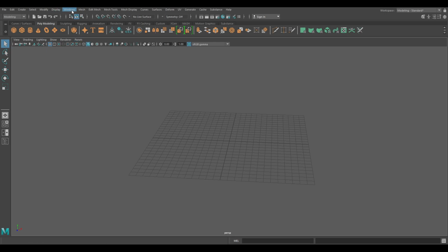So if I go in to set up my grid, I want to set up my grid in meters squared, which it is, and I've set the length and width of my grid to 13 meters. That means from this side here to over here is 26 meters all the way across. When it sets length and width, you should be aware it does that from point 0 here in the middle, and the length and width is just one side, like where I'm moving my mouse.